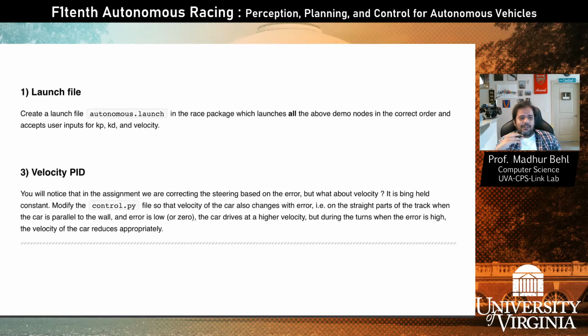And another thing I encourage you to compute is that in the template code and in the assignment, the PD controller I discussed is correcting the steering based on this lateral offset or the distance away from the wall, right? The velocity is being held constant.